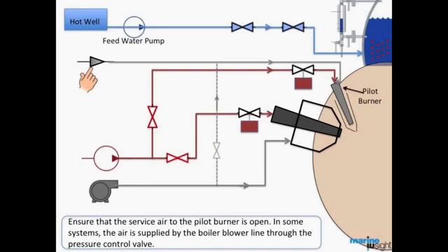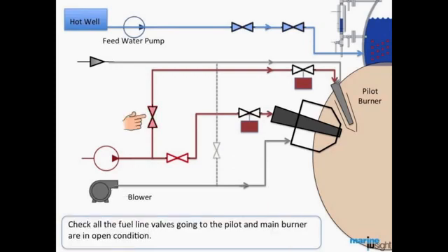Ensure that the service air to the pilot burner is open. In some systems, the air is supplied by blower line through the pressure control valve. Check all the fuel line valves going to the pilot and main burner are in open condition.